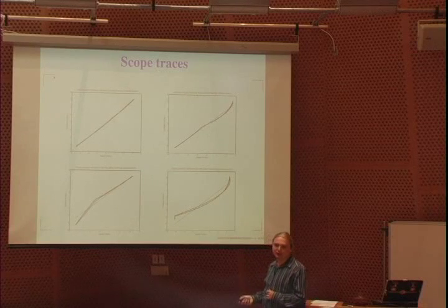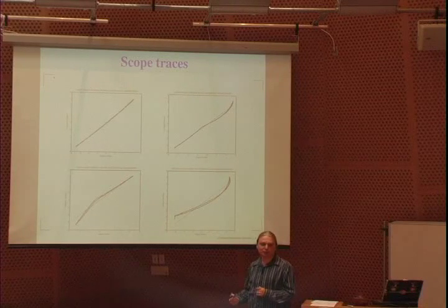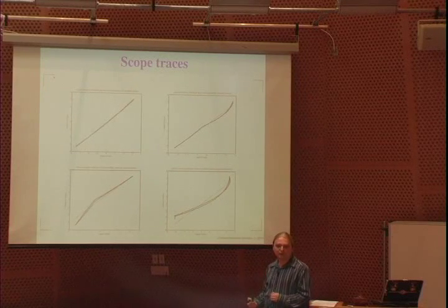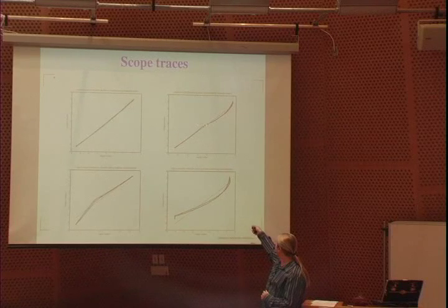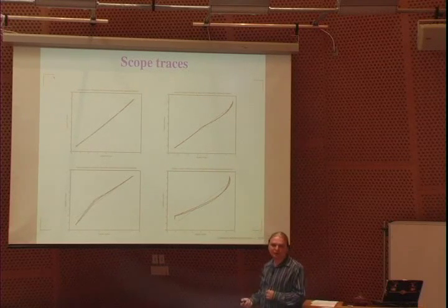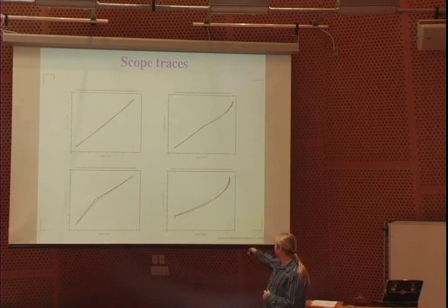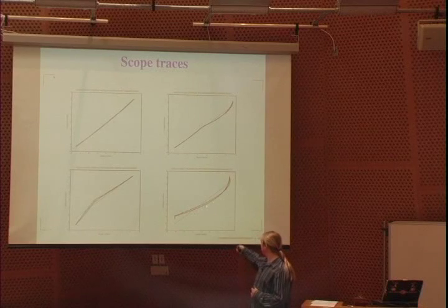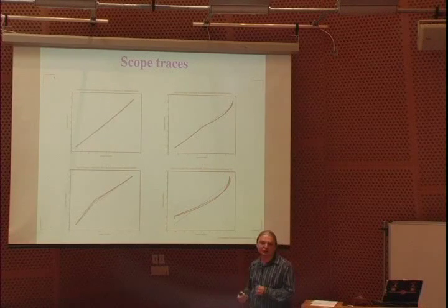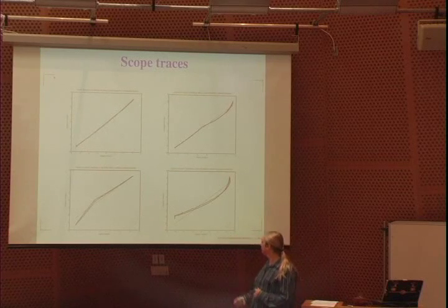If I swapped in the nonlinearity, the instant I swapped it in, I would get a large kink, and then the system would adjust, build a model of this, and then compensate for that. And so it would adjust to minimize that error. If I swapped out the nonlinearity, it would have a bad model. So again, the output didn't track the input. These don't overlap entirely because the system is learning as it's doing this. And then in the steady state, it would go back to that.